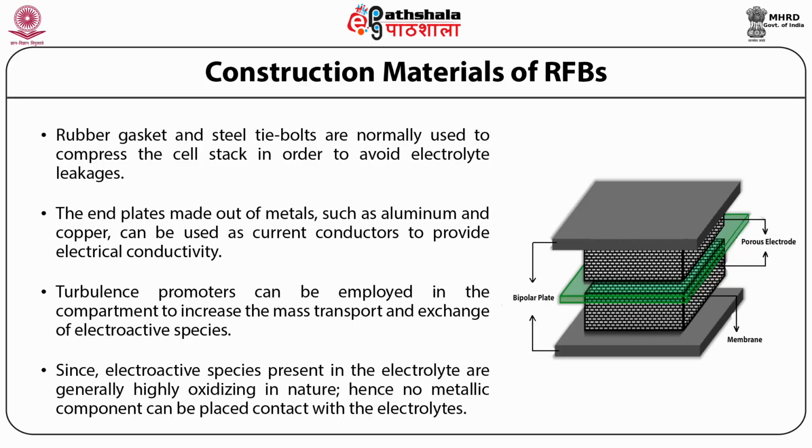Chemically resistant polymers such as polytetrafluoroethylene or PTFE, ethylene propylene diene monomer EPDM, polyvinyl chloride PVC, polyvinylidene fluoride PVDF, and acrylics are the typical materials used to fabricate the RFB electrolyte compartments.